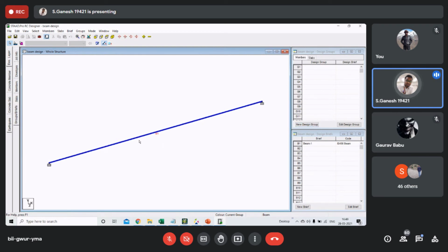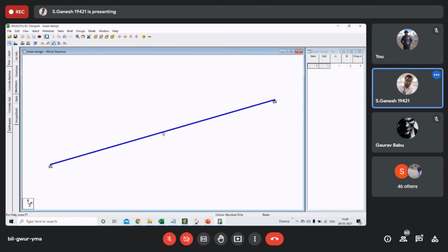So you want to assign this to group. So what is group now? You have some 25 members or 25 beams. Some members will be similar size, as I said already. Some beam sizes will be similar. So you need to give member IDs to that. That is called form members. So you need to define the member ID first, basically. And then now let's create a group for this. So I need to get our group members.